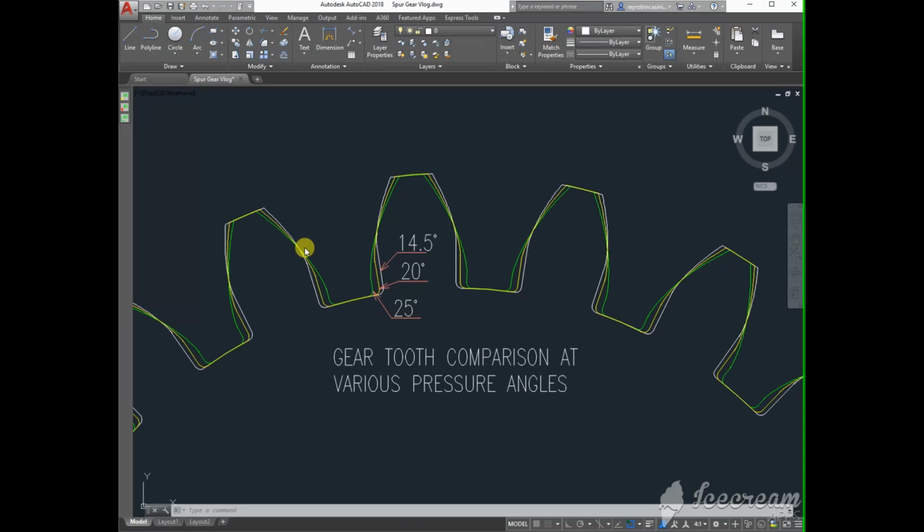Aside from its strength, meshing gears with high pressure angle have less tendency to have interference because of their narrow tip. We could summarize the advantages and disadvantages of having a high and low pressure angle. For a high pressure angle, the advantages are strong, it has high shear strength, and eliminates interference between gears. Disadvantages: less efficient, noisy, and heats up at high RPM.